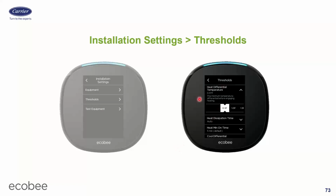So the first one we'll look at is the heating differential temperature. And this will also come up on the cooling side, so we can just talk about it once. But this is the amount of degrees that we have to exceed the set point before we're actually going to engage the heating. So if you have the heating set for 70 degrees, it has to drop down to 69.5 for it to kick the heat on. And then it'll run the heat until it gets back up to 70 and then shut it off.